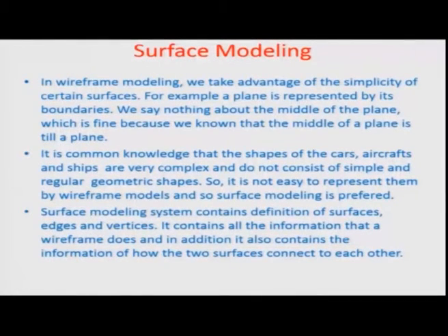So, let us go to surface model. In wireframe modeling, we take advantage of the simplicity of certain surfaces. For example, a plane is represented by its boundaries. We say nothing about the middle of the plane, nor do we have a data structure for that, but now we would like to do that through this approach of surface modeling.